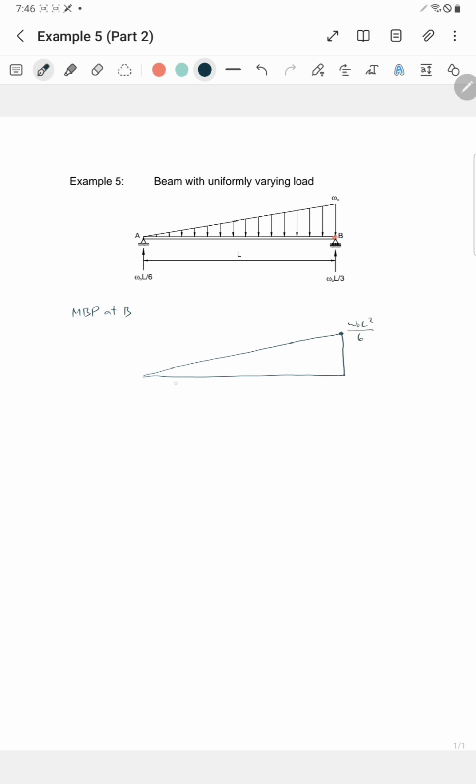And due to the triangular load, the moment by parts diagram is 3rd degree, starting from the tip of the triangle and terminating at B. So kapag triangular yung load, the degree is 3rd degree. And the moment is, the total load is 1/2 LWO, and its lever arm from right is 1/3 of L, or simply WOL square over 6.